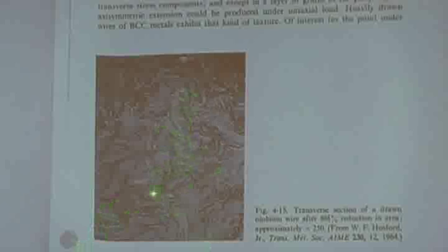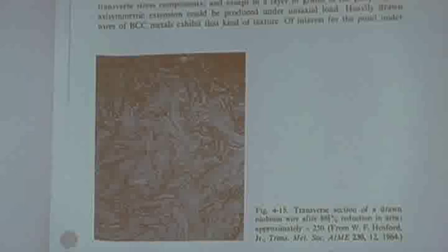But niobium is body-centered cubic, and if you draw a wire, it's actually symmetric deformation. You're going from big diameter to small diameter, and everything's circular, but it will have a 111 texture. If I think of BCC, it's going to want to align so the close-packed direction is in the axis of the wire drawing, and that means the 110 plane is at a slight angle, and when it deforms, it's going to deform like that tensile specimen that deformed into an ellipse.